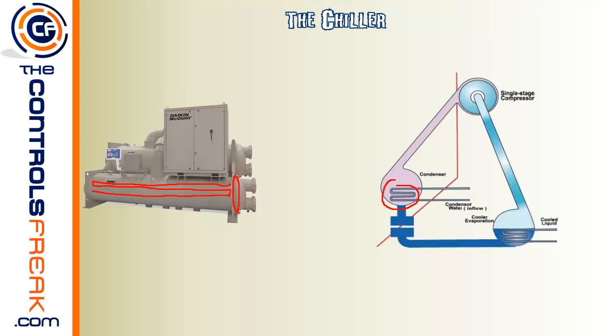And so if you ever hear somebody saying they were changing out tubes or they have dead tubes in the barrels and so forth, these are many tubes, and there's many of them. I've seen some chiller barrels that had literally 100 or more inside the chiller barrel. So there's tiny little tubes all throughout this chiller barrel. And that's where you get the water running back and forth through this barrel to do the heat transfer. So just a little bit of extra on the chiller. Let's move on to the next step.